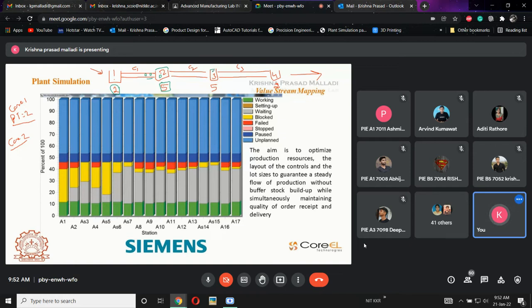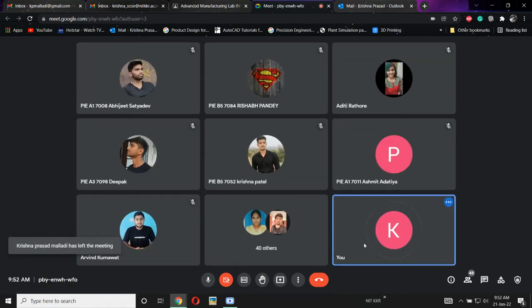Now what will happen for the next 3 minutes for this machine? There won't be any output. Why? Because the processing time of the third machine is 5 minutes. For every 5 minutes there will be only one part. But the fourth machine's processing time is 2 minutes, which means in 2 minutes the part will be completed and given to the output.